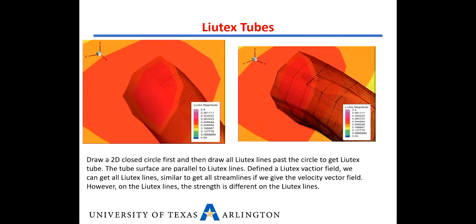This is the tube. This kind of could show the vortex structure. Isosurface cannot. Isosurface just says, in this surface, every Q is equal. In this surface, lambda 2 is equal. It doesn't mean they're a vortex tube. The vorticity, of course, is not.